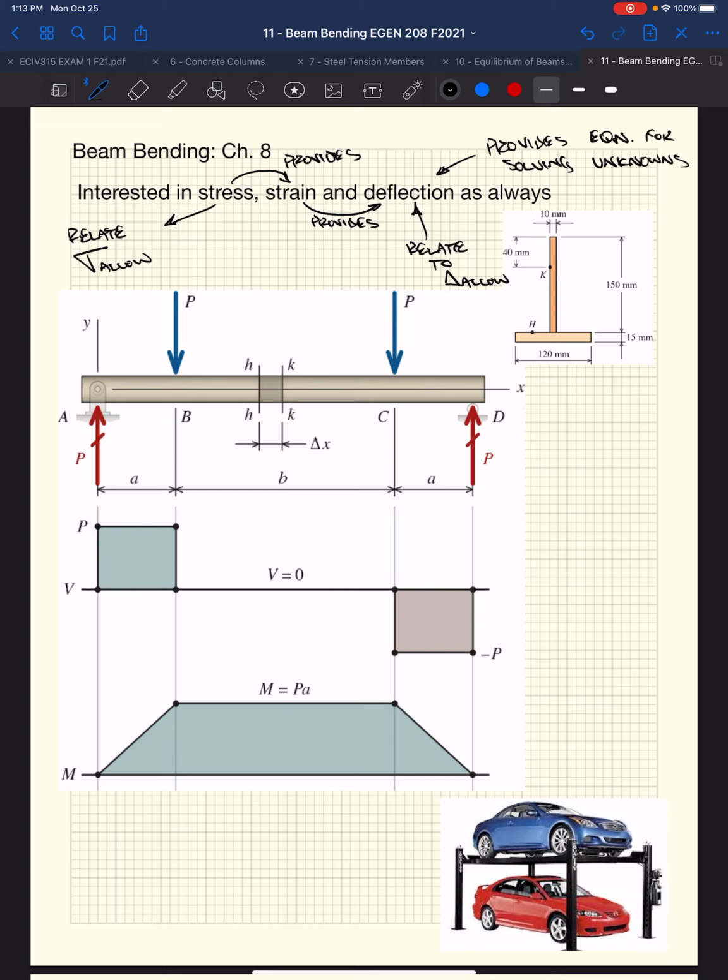Center of the building starts deflecting and becomes just a pool. And then that pool collects more water, which collects more water, which collects more water, and then pretty soon it falls down, right? You get things like that, you would check for deflections to make sure that when it's loaded with 2 inches of water, it doesn't start creating this pool, right? A little big kiddie pool up there.